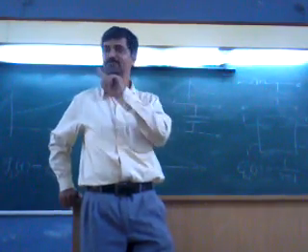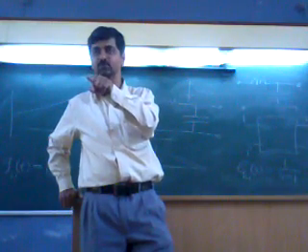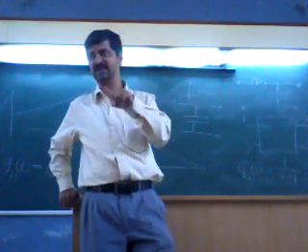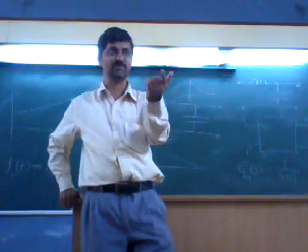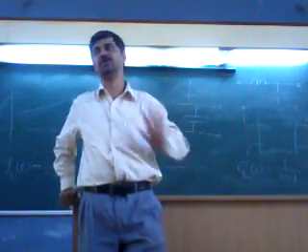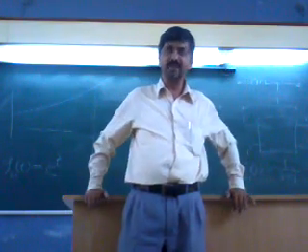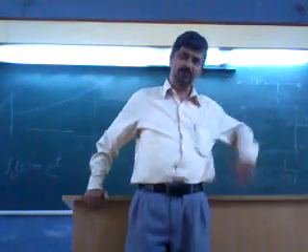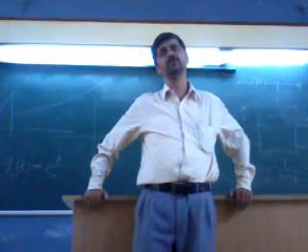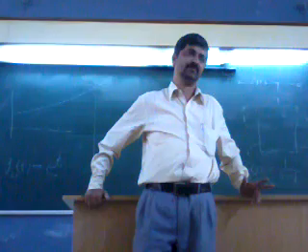But you can't decompose s squared plus 1 if only real roots are to be considered. But the moment imaginary and complex roots are allowed, s squared plus 1 is decomposed as (s+j)(s−j). So with complex roots allowed, you can get any decomposition. And by looking at the location of poles, you can conclude whether the system is stable, unstable or marginally stable.